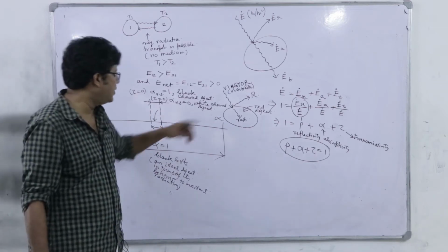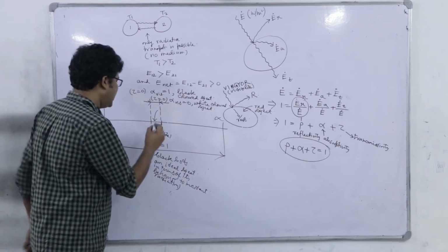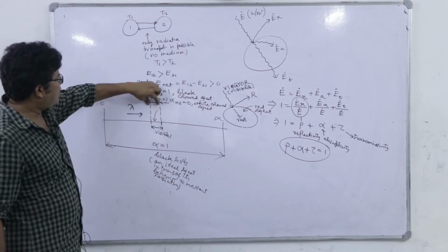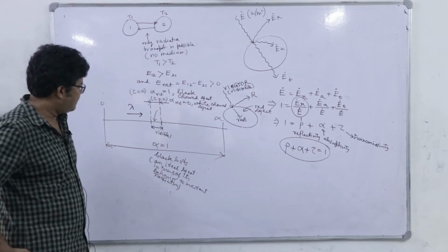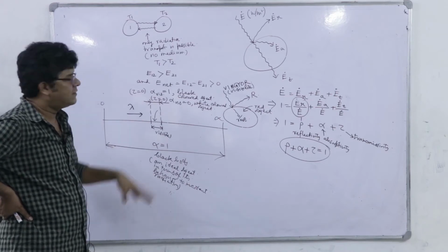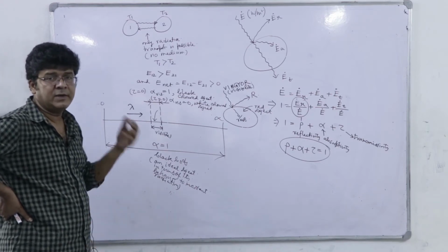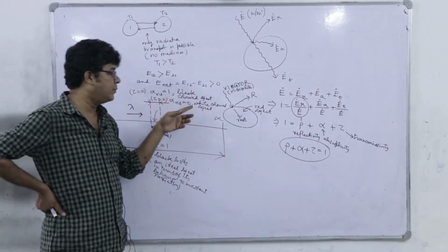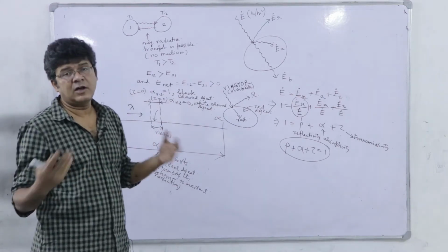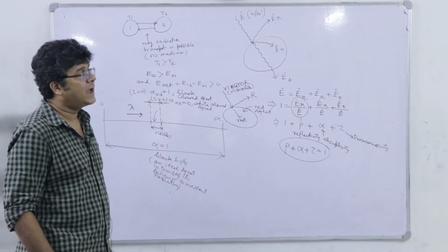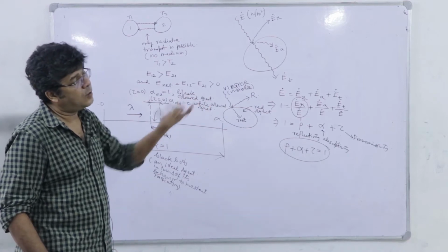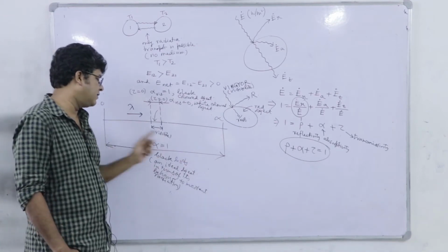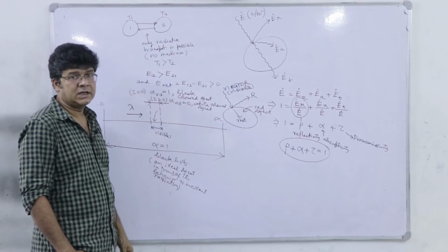So from 0 to infinity over this entire range of lambda, if over only the visible domain all the incident VIBGYOR spectra is being absorbed by this object, the body will appear black, but that is a black colored object. But if we think of a theoretical, ideal object which absorbs all the incident radiation over the entire wavelength range, it becomes a black body, right.